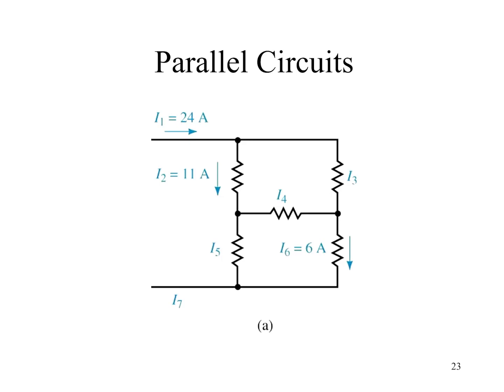So one way to start this is, let's suppose that inside this box is essentially a single point, which it is. As far as the source goes, this is a single current division node where I have 24 amps entering and exiting over here. So we know current entering has to equal current exiting. So this means that I7 would have to be 24 amps.